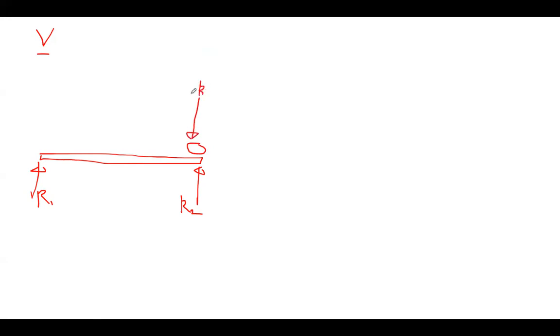Okay. If this is your beam, you have a beam or a bridge, usually with moving loads. R2. So, for you to compute the maximum shear, you just have to place the bigger load. I'll write here B for the bigger load, and then you have here the small load, okay? You have a certain distance A. Then, if it is R1, R2 is the maximum shear. Okay? So, take moment here at 1, then you can compute R2.